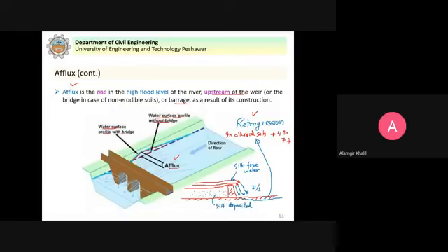Clear? Now, when silting is done here, behind the weir or barrage, this area gets silted. Clear? So when the upstream pond is silted up and no more silt can be deposited here, the water flowing under the gates of the barrage or over the weir will then carry the total sediment load, because no more silt can settle upstream.